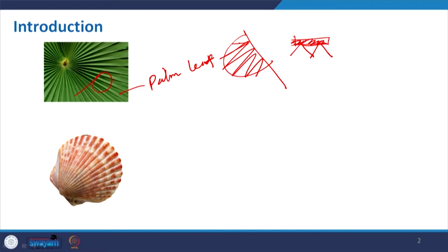If I make this section flat, it is nothing but a very thin plate, where applying load will make it bend. This is option 1, and in option 2, I just make a fold. So, all of a sudden it will increase the capacity of resisting the load on top of it.